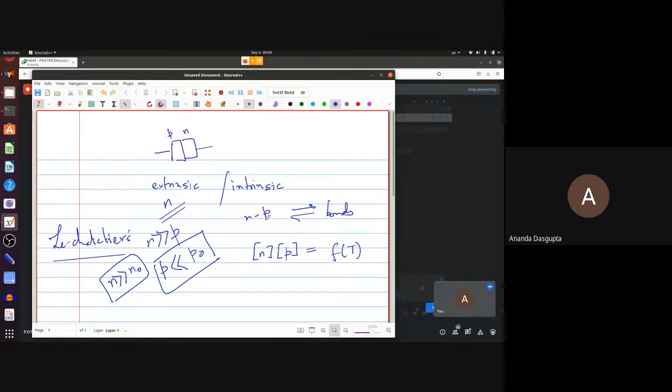So if you think that your diode can take say 4 amperes, you quote only 1. Now the reason why I say think is this. How do you know that a diode will take 4 amperes? You can't give a diode current until it just burns up, right? You can, of course, but then the diode is gone. You can't use it any further.